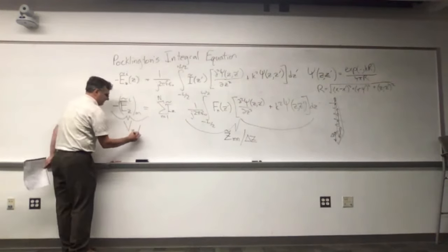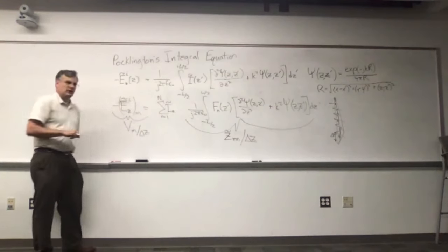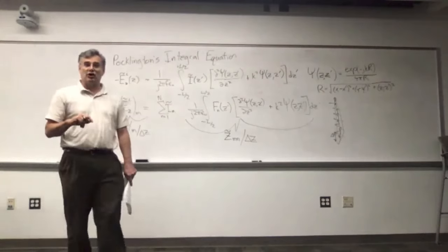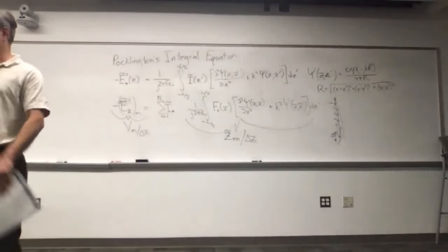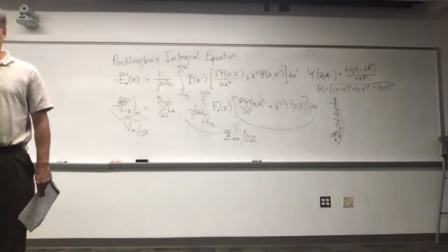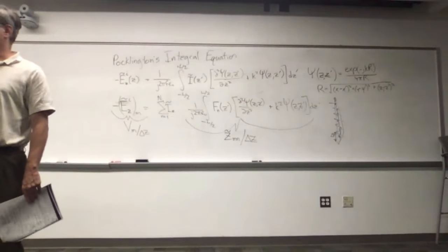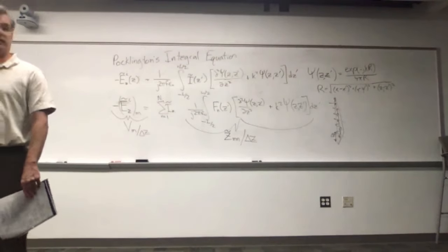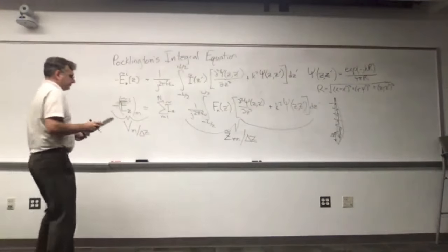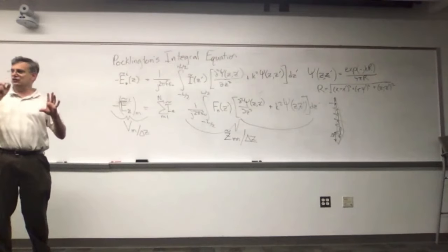And of course, I'm going to have to divide by delta Z to get this also into a field. Remember, field is negative the gradient of the voltage. So if I divide the voltage by delta Z, I get something that's proportional to the field. And I have to put a minus sign in front of it as well, because the E field always points from positive to negative voltage. So they're both samples along that discretized wire.